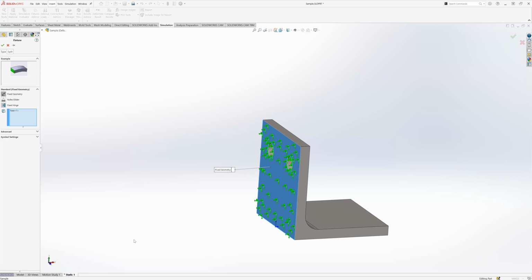So it can translate along all 3 axes, X, Y, and Z. It can also rotate. By applying this fixed constraint here, I've literally eliminated all 6 degrees of freedom from this part. Because, like I talked about last time, those inertial effects, which I believe is a 4th assumption for running a static study, mean your part can't just fly off somewhere when you apply a force. It has to be fixed to something, or your assembly.